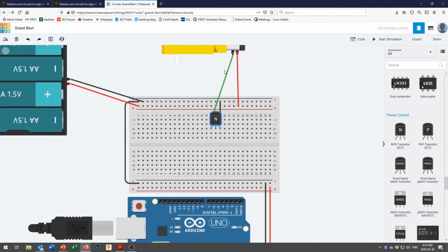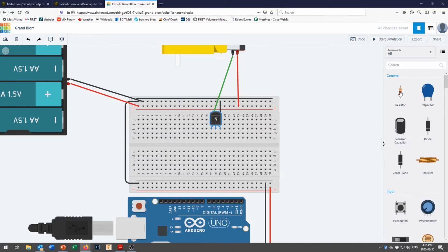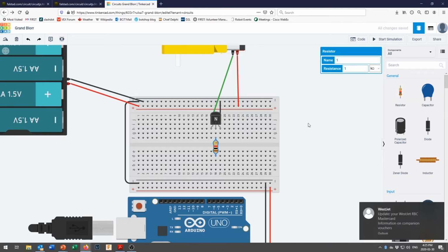So now what's happening, we want the electricity to come down here, up through here, down through right here. The transistor is going to act like a switch, and when the switch is on, electricity can come back that way and go back to ground. And we're going to throw a resistor in line right here. The resistor comes to the base.